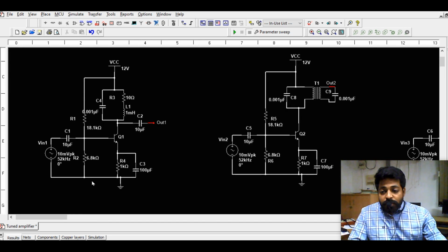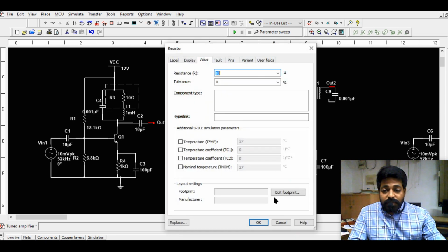As we know, the transistor virtual we took, the CE amplifier case, how we did the simulation, the same way I have to do the connections also. The emitter resistance and bypass capacitor, R1, R2, coupling capacitor and input are all the same. Only the RC, which I keep around 2.2 kilo ohms, is replaced with the tank circuit, where the capacitor is in one branch and the inductor in another branch, along with a small resistance of around 100 ohms.